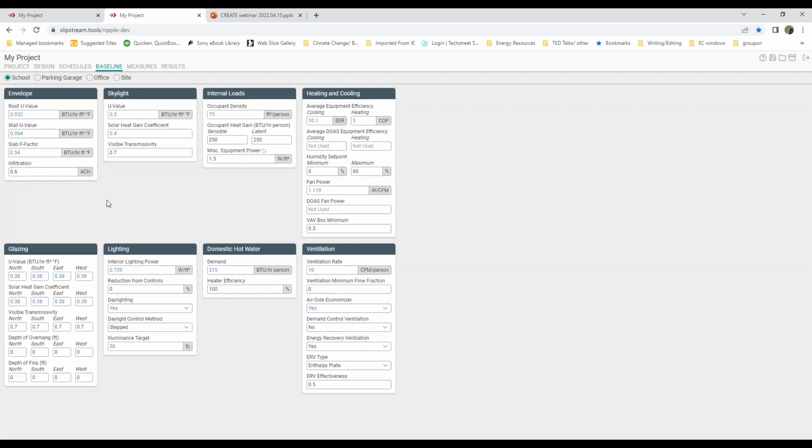And then you had asked, what would be the best way to model your particular building? Well, I'm sitting next to a pile of blueprints right now for that Mayan restaurant. The first step would be to get a hold of the building prints, and that way you have the ability to get the square footage, and you'd have to calculate the R value. So this is an awesome project. If you're going to model your building, you'd have to take some time to either work on it with your students side by side, or set it up and find a lot of those variables on your own.